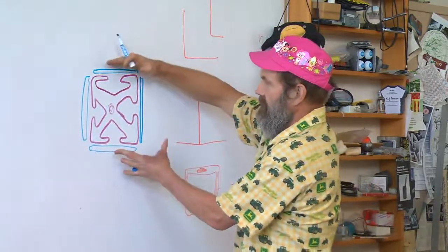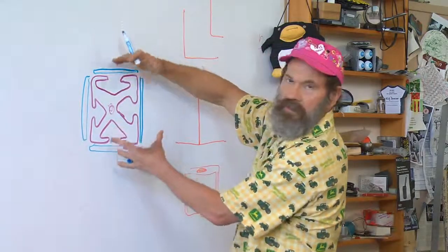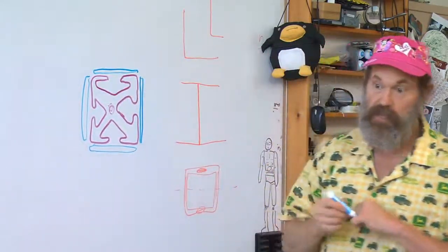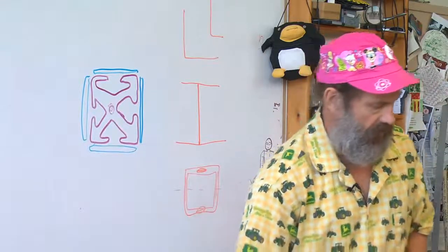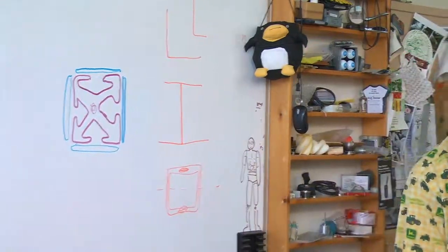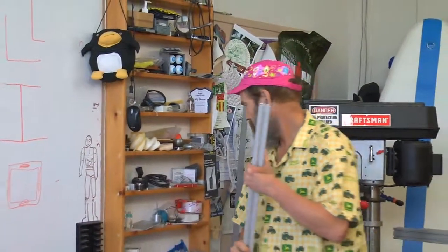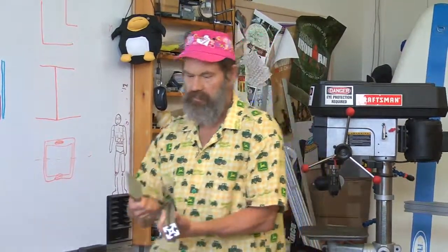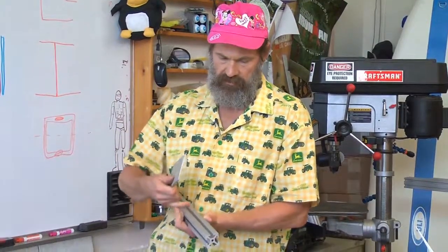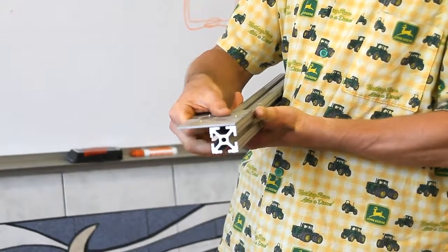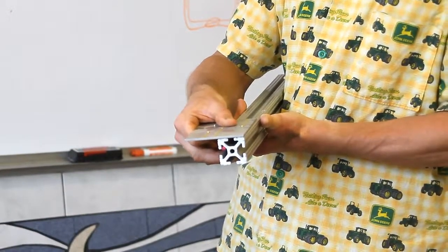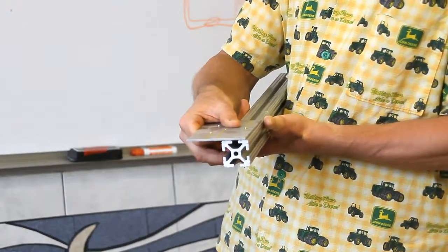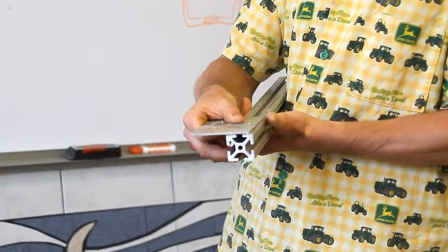Indeed, I would also be adding mass far away from the neutral axis for bending resistance. There's a couple ways you could envision doing that. You can envision building your entire machine out of this stuff and then taking thin sheets in the parts that are exposed and attaching them. And how would I attach them? I don't want to spend all the money on bolts and nuts and putting it all together.